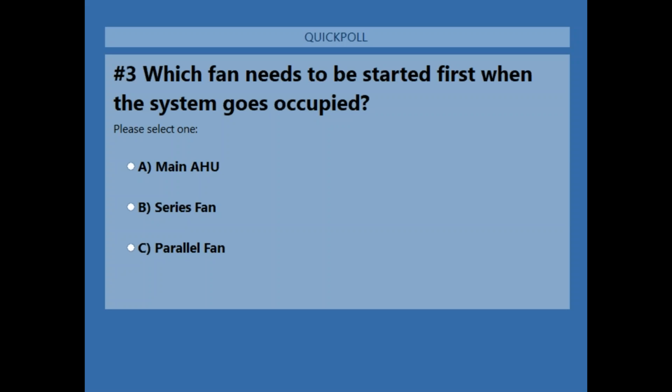That's kind of questionable. So the plenum cavity should be relatively clean, right? Don't make the plenum cavity be like your basement crawl space or something weird. It should be relatively clean. You do not need a filter on there when you're operating it. It's only there for construction time.